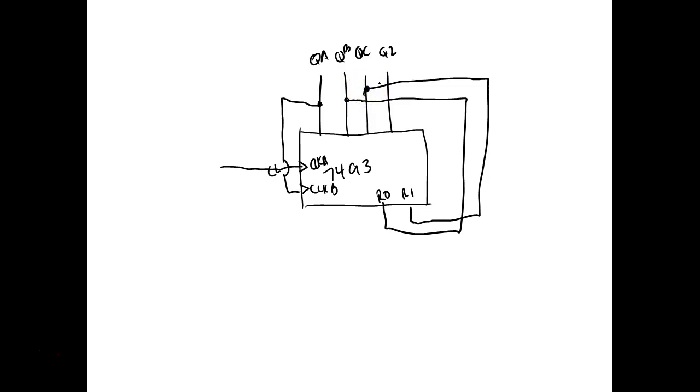So here the QD output wouldn't even be used because we're never going to get that far, right? So what are we resetting on? Okay, but what number? So we'd be resetting on a what? So I start counting. What, somebody said it? 6. We'd reset on 6. So this would be a modulus 6.